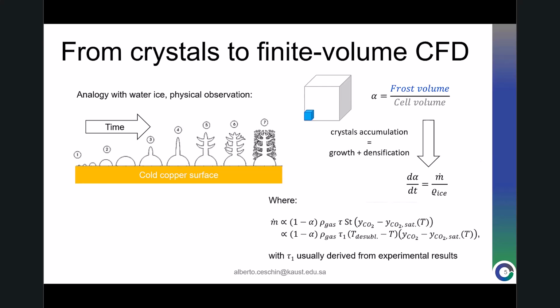This rate will be for sure proportional to the saturation rate according to equilibrium. And we can add also one more contribution from the Stefan number, which is just the difference in enthalpy divided by the latent heat. We end up with another gradient of temperature that is another driving force, especially important at lower temperature.